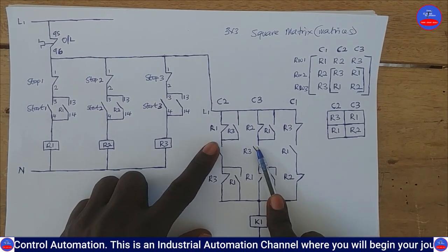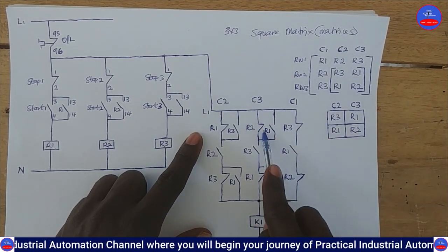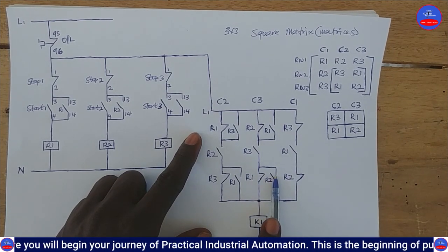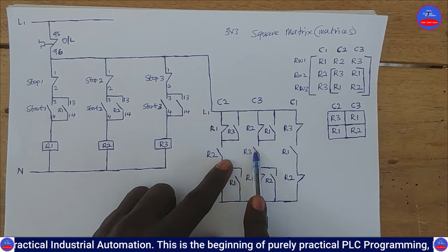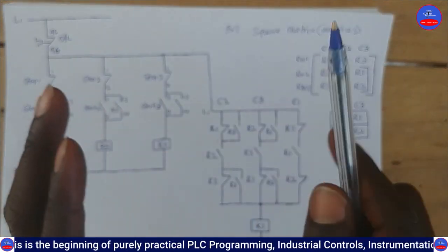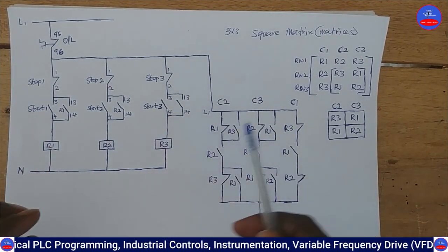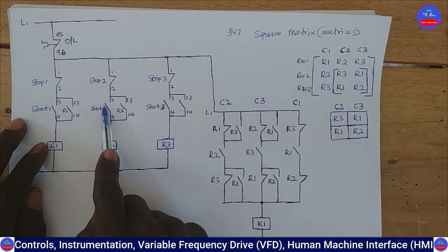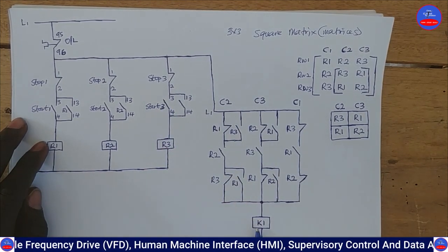This side also closed. And don't forget that our R2 and R1 are also already energized. So we have open contact, close contact here. Open contact, close contact here. The time the R3 also energized, it means that this side closed. So we have two close lines here. They are all serving the same purpose. Do you understand? So now we use start 1 to energize the contactor, you use start 2 to de-energize it, and then we have used start 3 to energize it again.